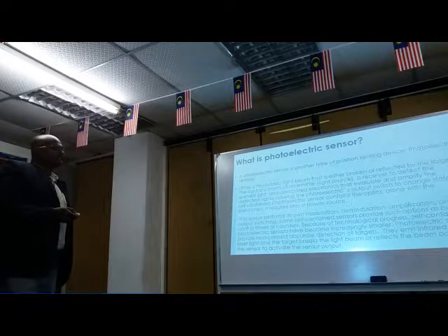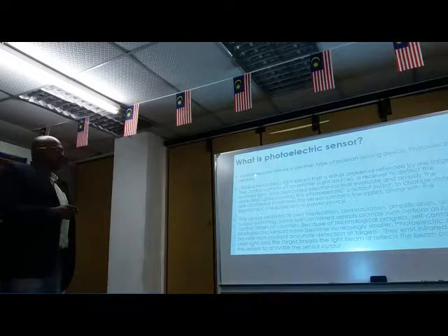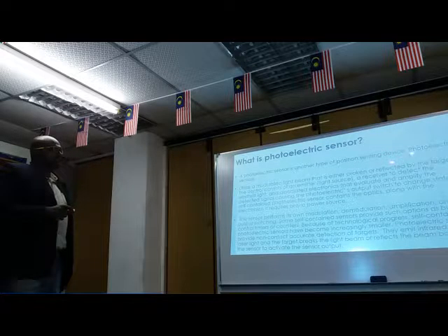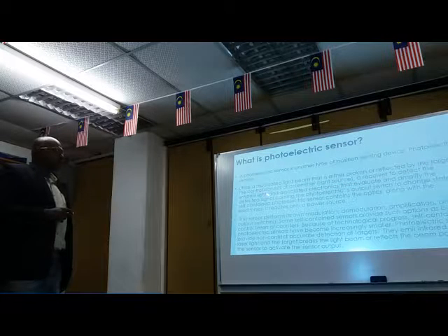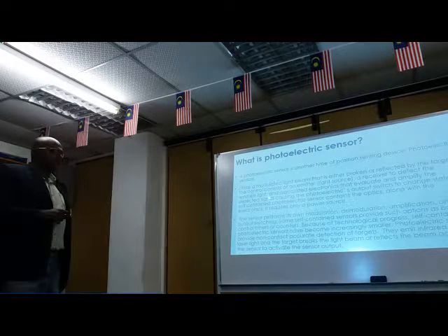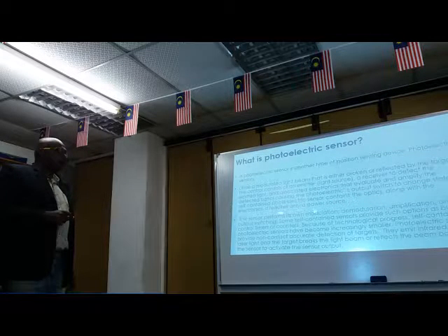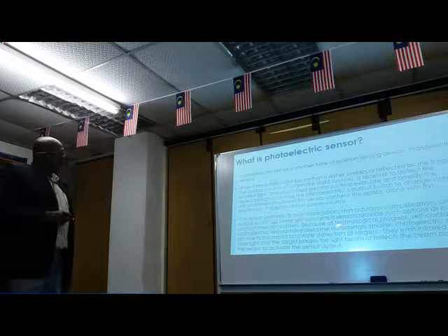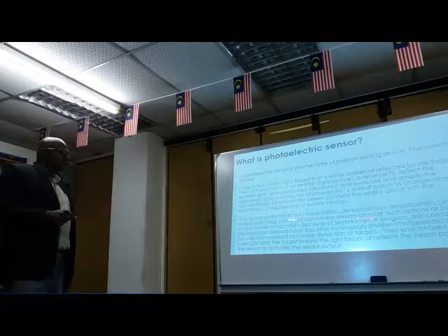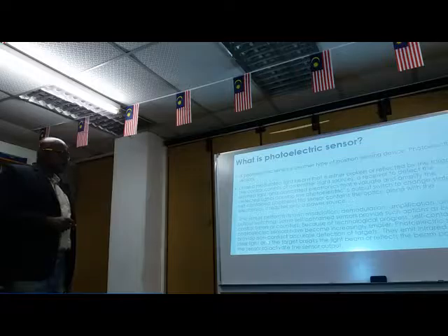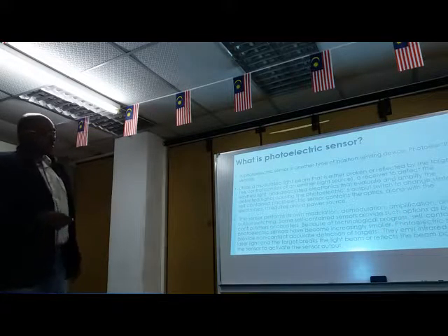Next, we go to another sensor that we use for this project, the photoelectric sensor. A photoelectric sensor is another type of positioning sensing device. Utilizing a modulated light beam that is either broken or reflected from the target, the control consists of an emitter and a receiver to detect the emitted light, and associated electronics that evaluate and amplify the detected signal, causing the photoelectric output switch to change state. A self-contained photoelectric sensor contains the optics along with the electronics. It requires only a power source. So the sensor can actually perform its own modulation or demodulation, amplification, or output switching. So this is the benefit of the photoelectric sensor.